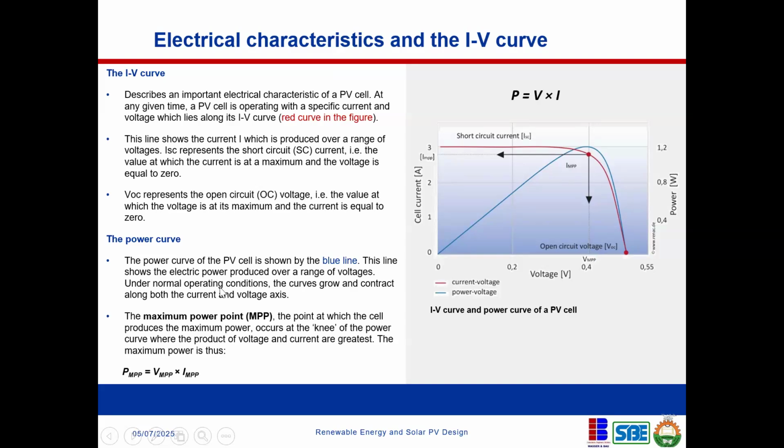Now, when you see an inverter, or charge controller rather, of course some inverters now have an inbuilt charge controller, in which case it's called a hybrid inverter. When you see a charge controller that is an MPPT charge controller, what that simply means is that it can automatically regulate this voltage and current to give the maximum power. That is the meaning of MPPT charge controllers. It can automatically find it.